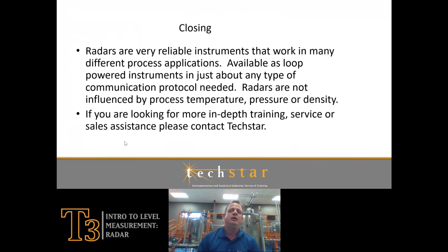So that's really the gist of what I wanted to talk about in our technical discussion here. In closing, a radar is a very reliable instrument. They're available as loop powered, and in many different protocols such as Foundation Fieldbus, Profibus, and Modbus. They're not influenced by process temperature, process pressure, or density.